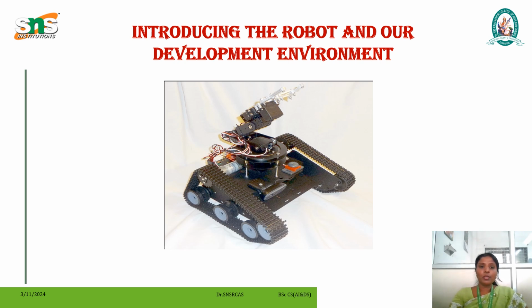If we want to go straight ahead, we set both motors to the same forward speed. If we want to travel backward, we reverse both motors the same amount. Turns are accomplished by moving one motor forward and the other backward, which makes the robot turn in place, or by giving one motor more forward drive than the other.